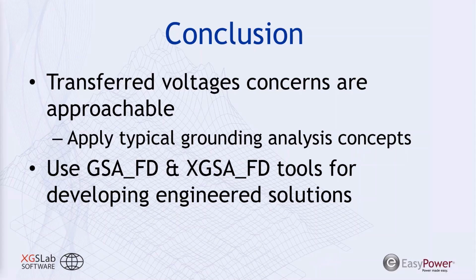What I'll say is the GPR isn't like the most accurate methodology for measuring the success of your grounding system. Really what we are looking at is how well two voltages match each other, meaning the voltage of the Earth's surface and the voltage of the thing that you're going to touch. That said, a higher ground potential rise can allow a higher touch voltage. So the GPR will correlate to the touch voltage and correlate to the transfer voltage hazard, but it isn't a direct indication of how significant hazards may be. So for that reason, there's that disconnect between the two standards.